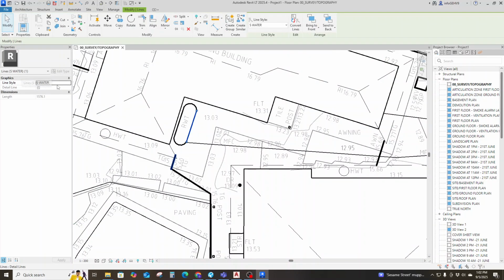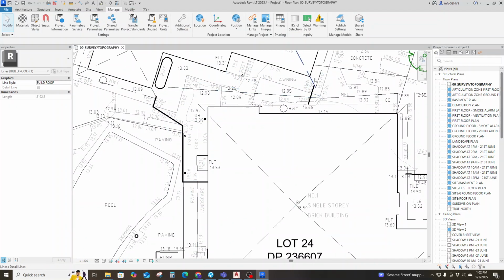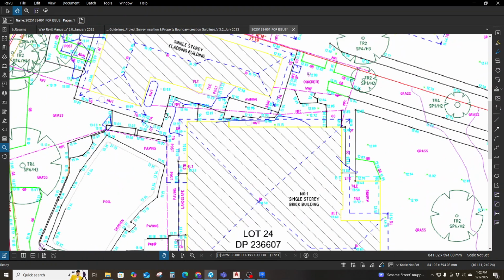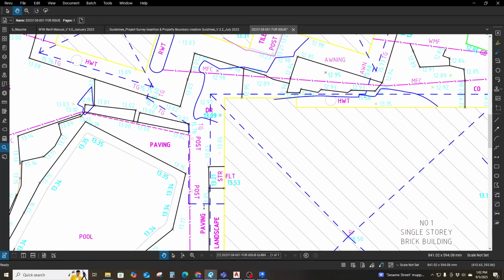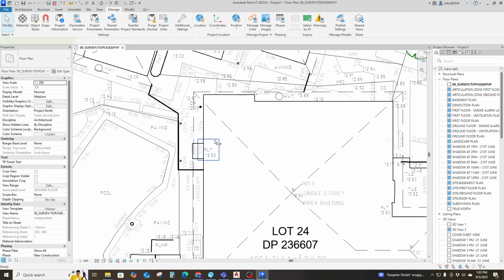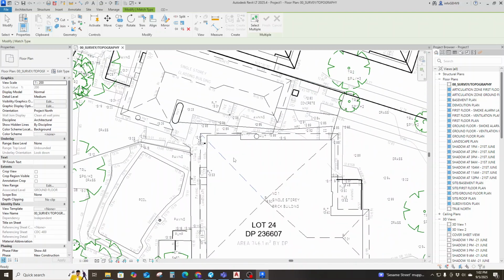Okay. All right. Again, the rainwater tank. Let's see, this is S water. We can make everything else 2. And this one is build roof. This roof is going to be a dash line. So let's open our PDF and see how the roof is shown over here. You can see this is the roof, I'll highlight it for you, that is going over here connecting, and then there is another roof line over here. So we are going to match this with the roof line type. So match, and then we say this roof, this, and this. All the roof lines are adjusted now.